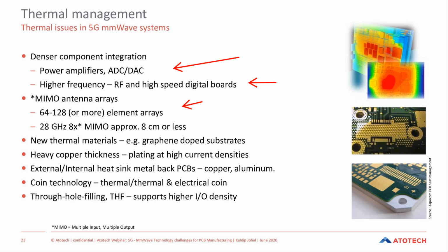But one of the ways that the PCB companies have been looking at this is if we look at, say, thicker copper plating, heavier copper, and so instead of just plating the 25 microns, even go in at a thicker 30 microns, etc. But again, with some of the PCBs, you've got to look at through hole and the aspect ratios and the performance of the throwing power to be equal to 100% or better.